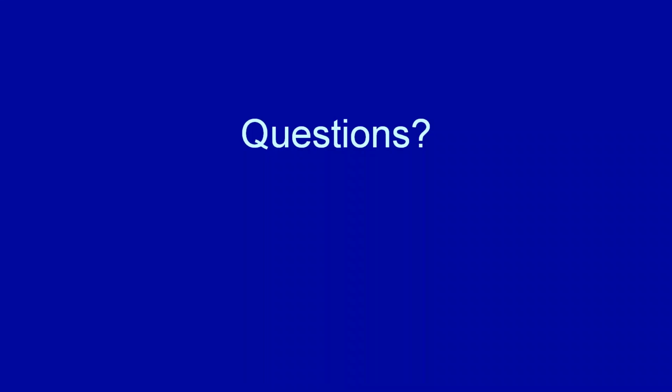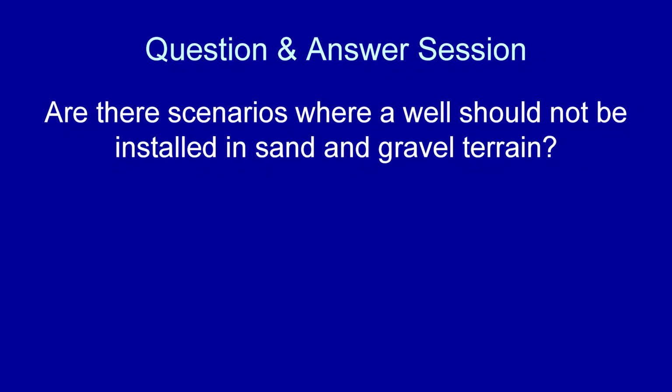We're back to potential questions. I do have a few of those. One is, are there scenarios where a well should not be installed in a sand and gravel terrain? The answer being yes, if in fact you know that the water chemistry is going to be of such a poor state that it would cost too much to build a treatment facility for it. Now this could be if you are proximal to swamps, or now called wetlands.